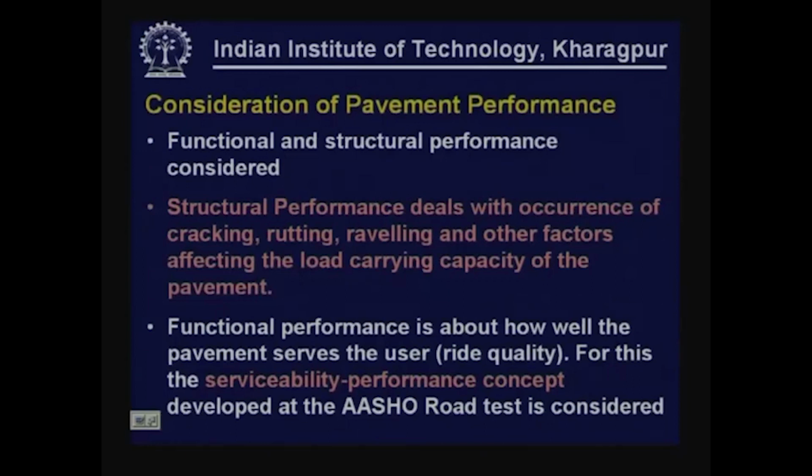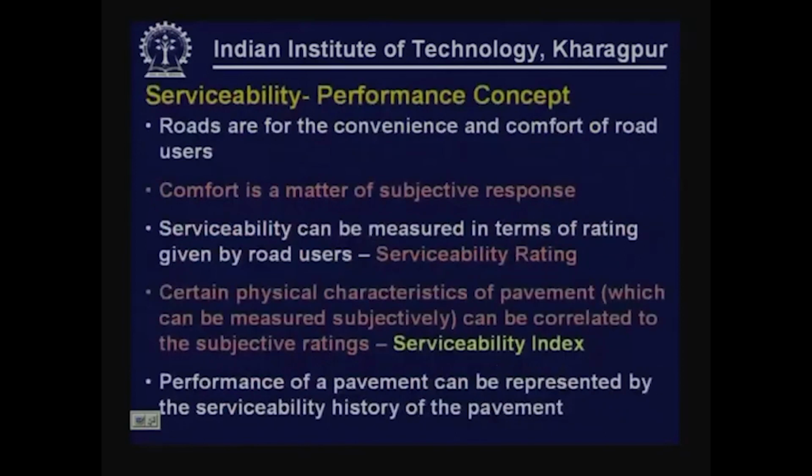In fact, this was a concept that was developed during the AASHTO road test. What is the serviceability performance concept? We know that roads are for the convenience and comfort of the road users. Comfort is a matter of subjective assessment. What is comfortable to me may not be comfortable to you, but when you have the collective assessment of a given road by a number of panelists or users, we will get some idea about how a particular road is rated by different people and how the rating of a particular road is different from the rating given by the same panel to another road having different condition.